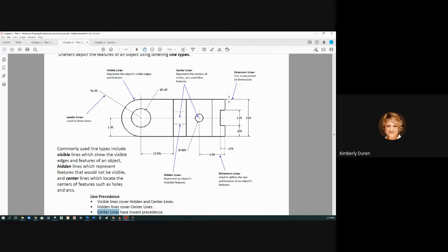These are called extension lines that extend these away, and this happens in architecture and civil too, in order to keep these things from overlapping. You put usually the smallest dimensions closest and then the overall very last. So you could have multiple rows of dimensions here, and then you just try and line them up so that it's really easy.